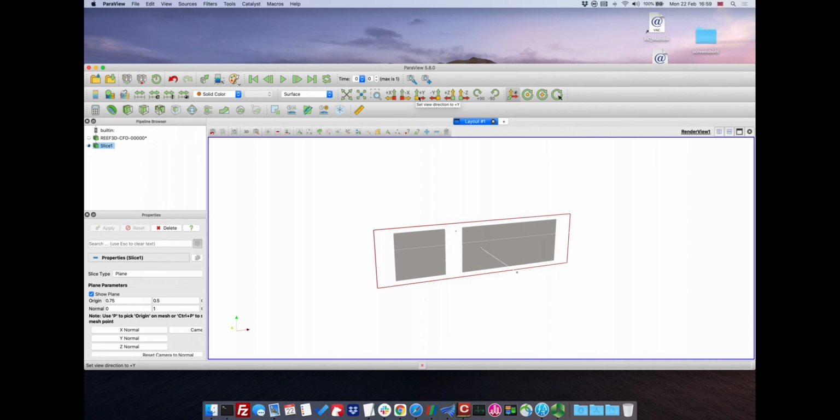What does that mean? The letter that is shown there refers to the axis that is going to be hidden from view. So in a Y normal plane, when we are looking at the XZ plane, what we see is the positive and of course the negative X-axis, and positive and of course the negative Z-axis. What you don't see is the Y-axis. If you switch to -Y, you see we are looking at it from the other side. Similarly, +X, you will see nothing because we have taken a slice on the XZ plane. +Z, the same thing, you see nothing.